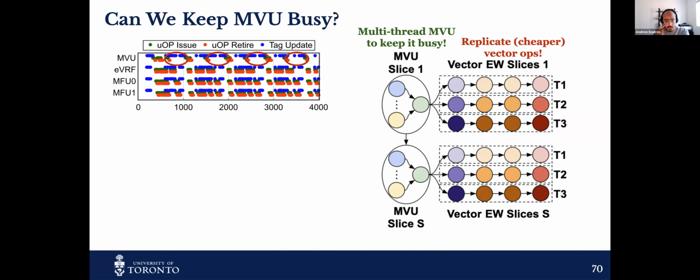And then we thought, okay, we can actually keep the NPU busy by interleaving the execution of different models at the same time. So you execute the matrix vector operations of a model, you send it out to the other modules, you switch to a different model. So you can think of it as the NPU being multi-threaded. It has multiple threads running different models and switching between them.